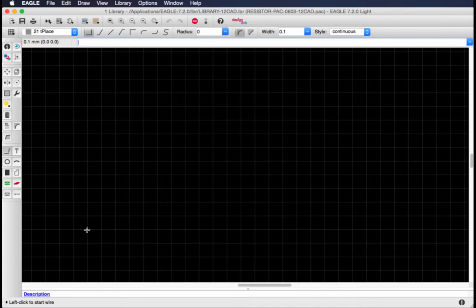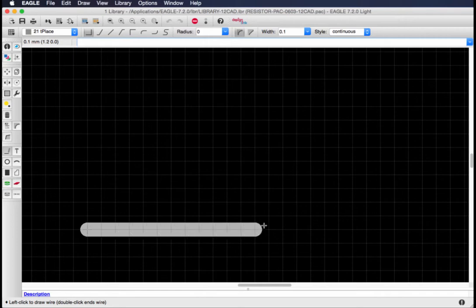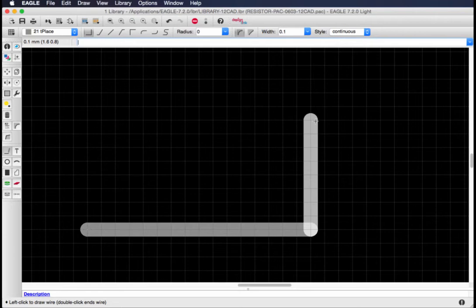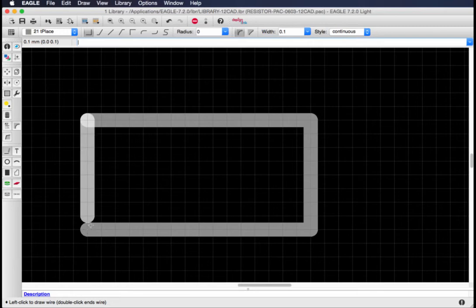And now I can start at this cursor in the schematic window, and I can keep an eye at this top left corner and create a 1.6 millimeter line. If I keep going, it's 0.7, 0.8, 0.9, 1.6 right here, and then I can click. Now I need to go up by 0.8, the width of the resistor. I have 0.1, 0.2, 0.3, 0.5, 0.6, 0.8. And then click, and then I can continue back and finish the rectangle and click.